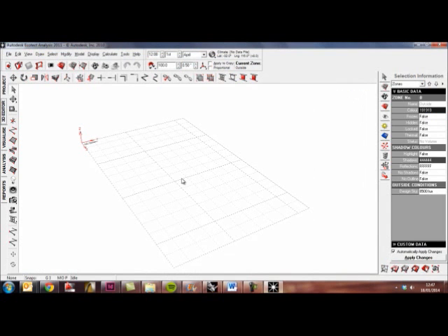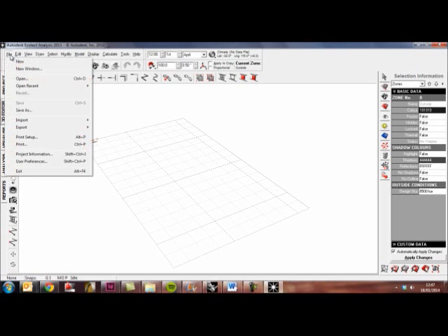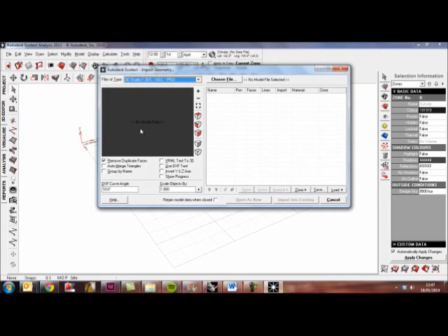So here we are in Ecotect. Ecotect obviously a different format to Rhino, but a very, very simple tool. So we're going to import the three different 3DS models that we've exported from Rhino. To do that, File, Import 3D CAD Geometry. You press that, you get a second window here, which has various options, none of which you particularly need to concern yourselves with at the moment.